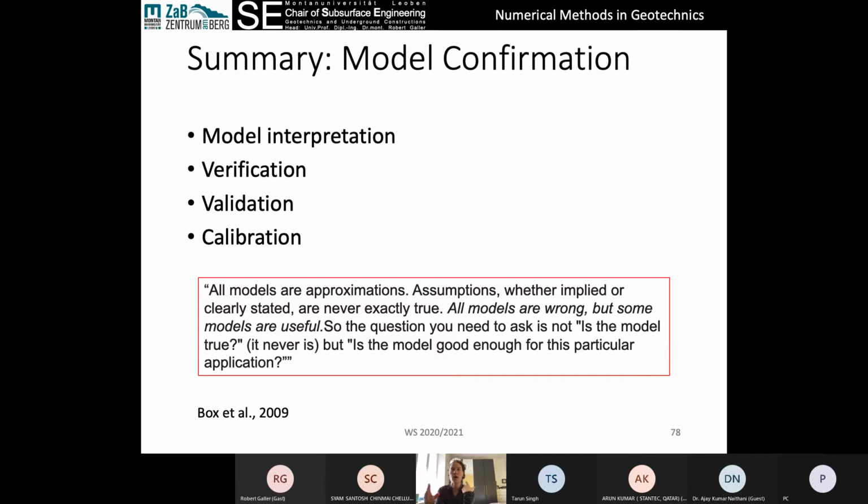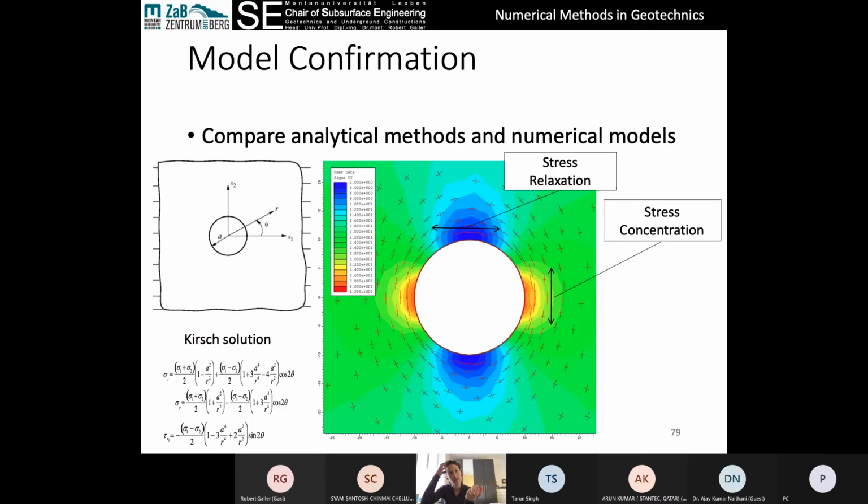And that also requires a little bit of engineering judgment. If we're in a fractured rock tunnel at shallow depth, and we're seeing a tremendous amount of failed elements, then we might be thinking, I don't think my material properties are quite right.